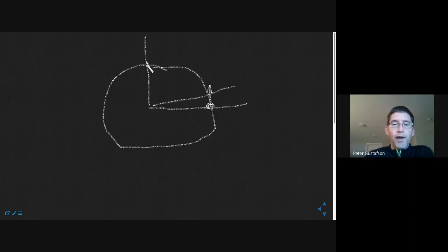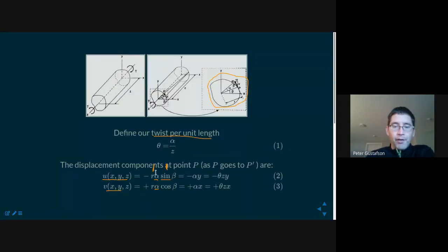If I use this point and now it's sweeping through this angle, then that component is entirely horizontal. And so you can see this angle beta now matters. If you're somewhere in the middle here, if this is your initial position and now it's moving this direction, it's somewhere in between entirely vertical and entirely horizontal, and that is governed ultimately by this geometric entity, R sine of beta.